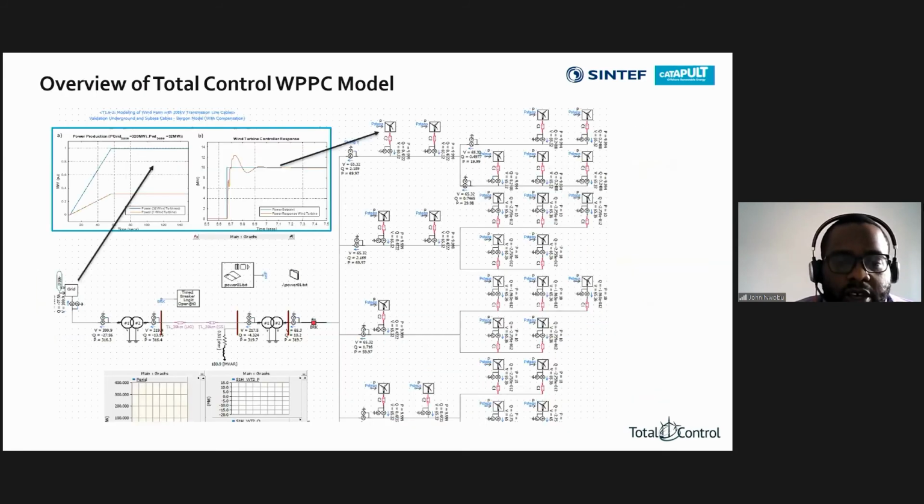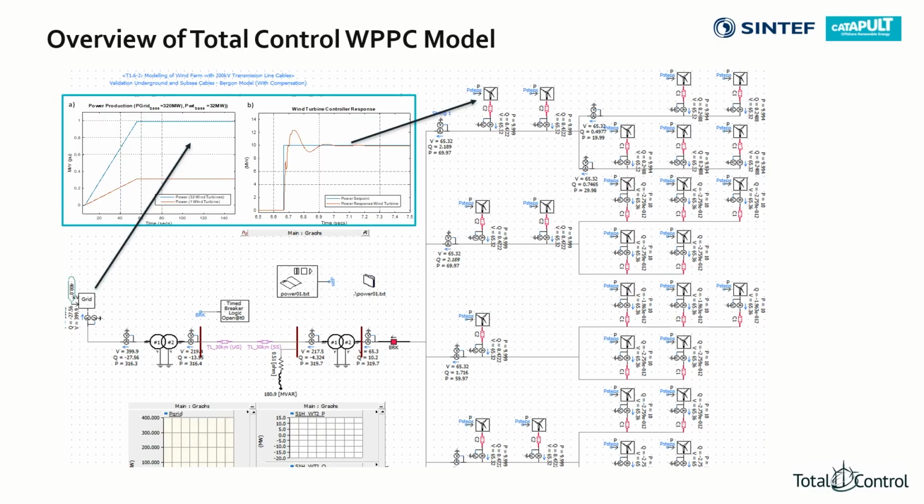And this slide is just an example of the model already built. Each of the wind turbines, as you can see there, has a detailed electrical powertrain model, which has the power control aspect and the current control aspect with the vector controls in there. It basically has your power production strategy curves and can respond to different wind speeds and give different performance outputs. As well as that, you have all the different electrical elements, including the filters and the transmission cables and everything all modeled in there at the converter side.